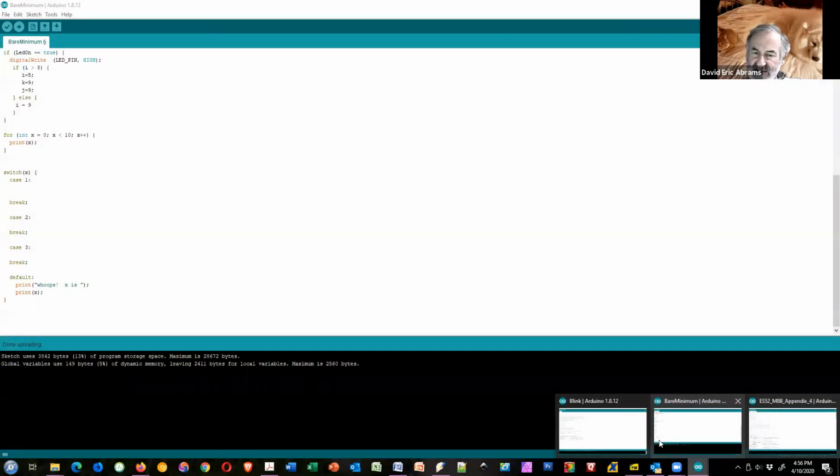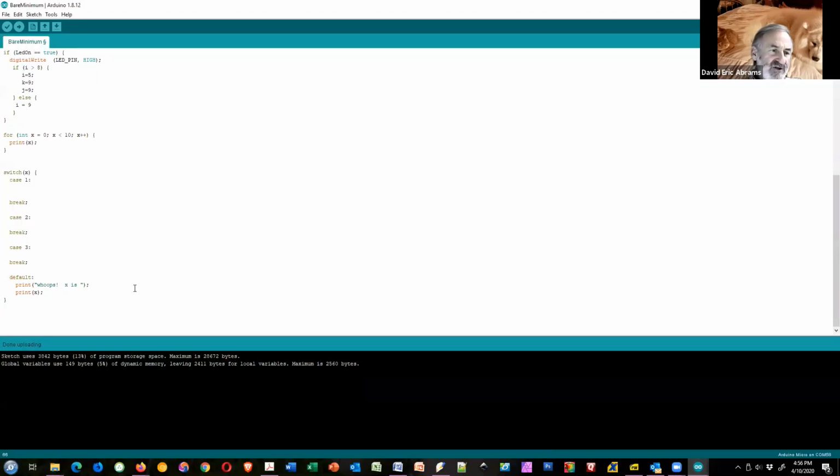One of the things that's tough about using the Arduino is there's not much debugging facilities. There's no way to see what's going on. You have this LED, so we'll often use the LED just to tell us we got somewhere. What we'll do in setup is we'll turn the LED off, and if we run our code and it doesn't work and we can't tell why, we'll go somewhere early in our code and say turn the LED on, and if the LED comes on, we know we got there. Or if something happens, we'll turn the LED on.